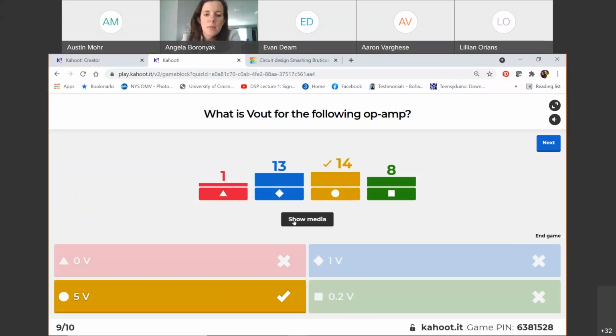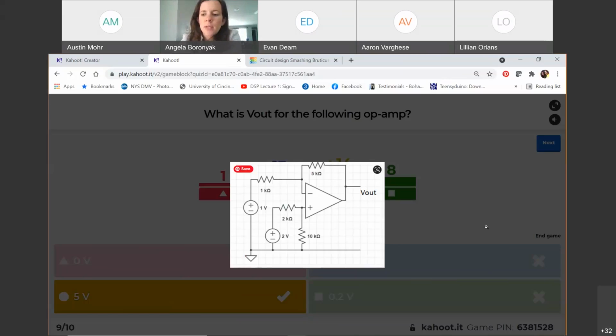Okay, almost even split here. What type of op amp was this? As a hint, it was one of our 4 general op amp circuits. Any ideas what type it was? Yeah, mixed answers between inverting and non-inverting. Well, I have a voltage source that goes in my inverting input, but my non-inverting input, if it's an inverting amplifier, would just need a resistor to ground. I've got a voltage source here and resistors that I could have current. That's not the same. Good, Leah.